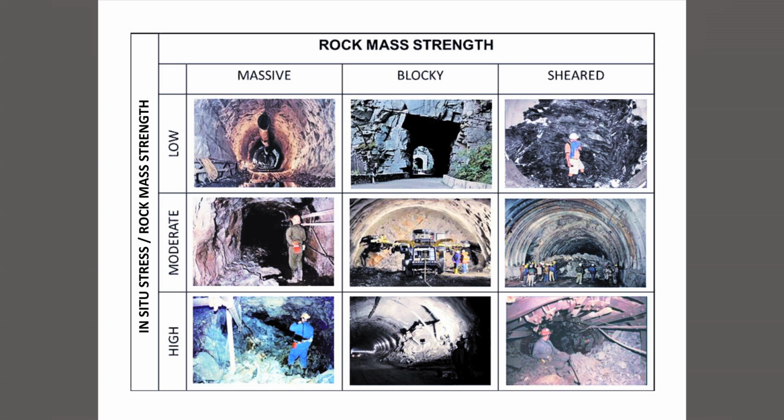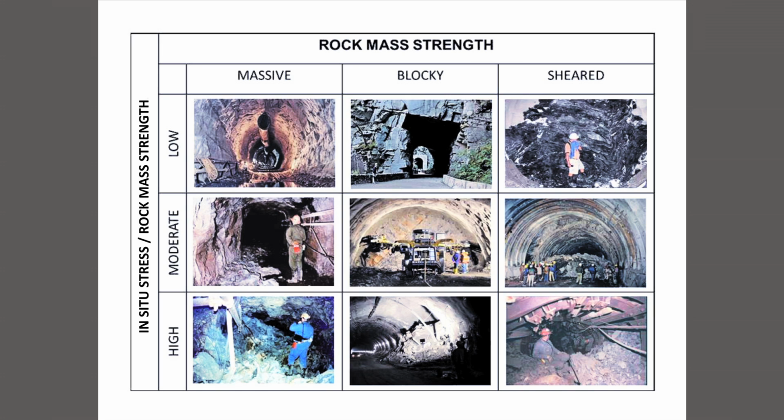And as the stresses become higher, as you go deeper down, the rock is more closely interlocked and much more stable. On the right-hand side, the column which I've called sheared rock, is rock that has been tectonically disturbed, generally in alpine environments or in the Himalayas in India, the Andes in South America, the Rockies in North America. These have been formed by huge movements of the crustal plates, and in this mountain formation process, they have been severely deformed and in many cases broken the rock up into almost soil-like characteristics. And so that's a special category which obviously gets worse as you go deeper.